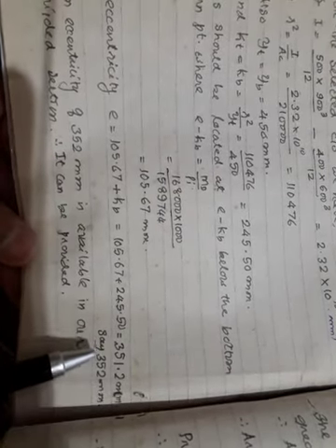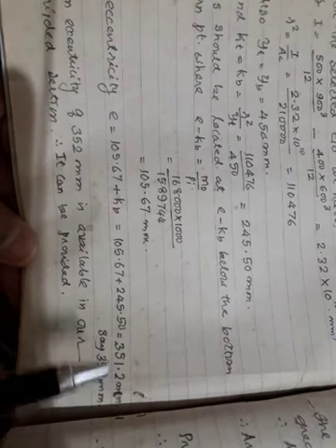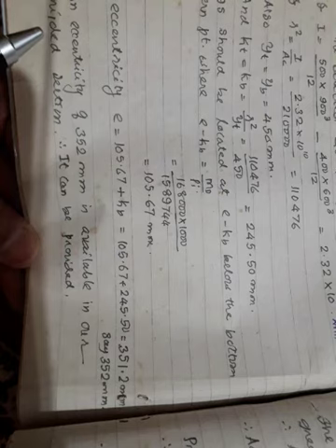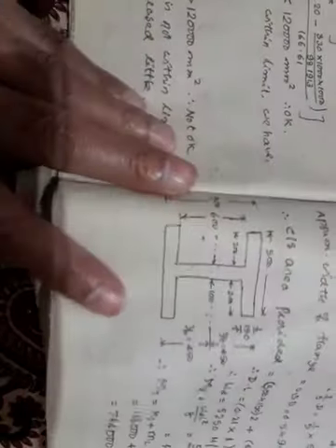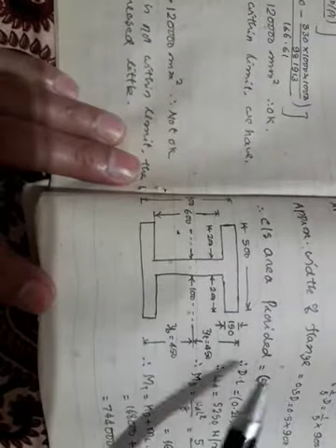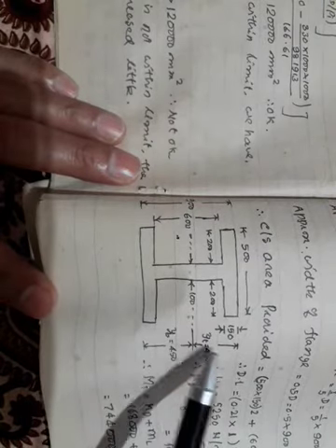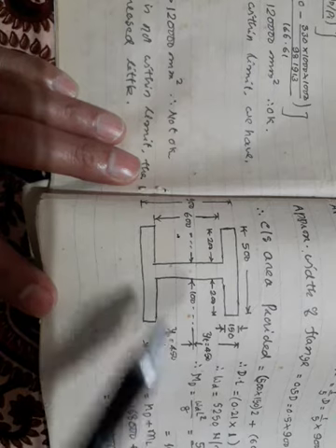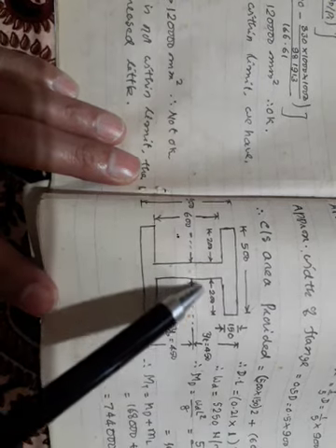So now this 352 mm eccentricity is available in our provided section. See, now I will show you, our cross section provided is like this. Is it right or not? Your Yt value is 450, Yb value is also 450. So this is the CGC. Am I right?